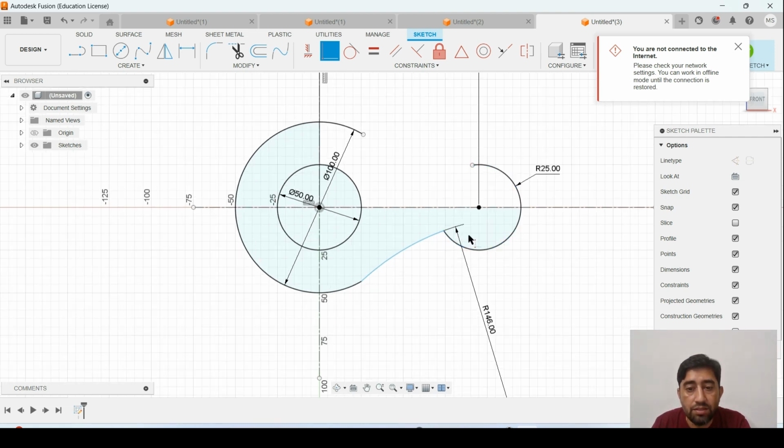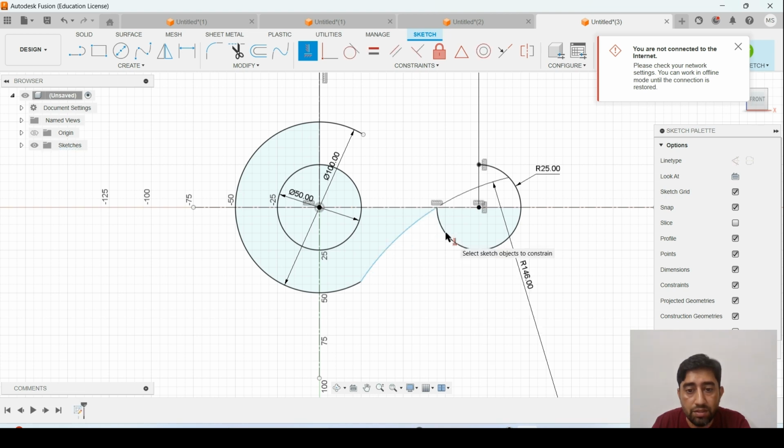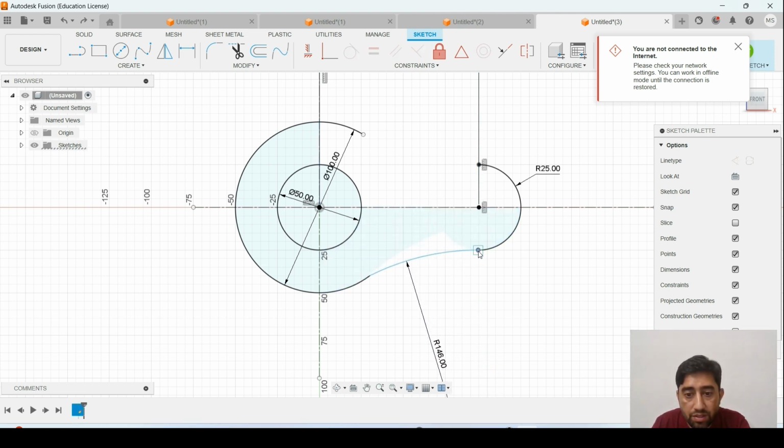Now our sketch is a little bit distorted because we haven't defined the end points of this 25 mm arc. So go to coincident, go to horizontal, not coincident. Click this and this. So now they are vertically aligned. Click center and this point, as it is close to horizontal, so it moves towards the horizontal line, but we do not require it in the horizontal. We require these 3 points vertically aligned. So we manually move this, and now horizontal vertical constraints are applied.